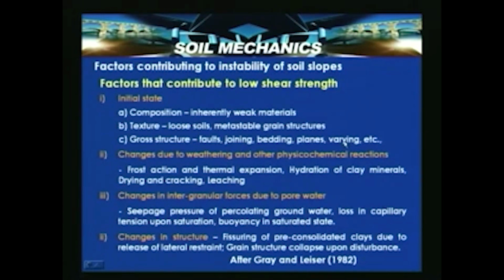Warping, planes, bedding, jointing and faults are the gross structures within the soil. Changes due to weathering and other physico-chemical reactions, frost action and thermal expansion, hydration of clay minerals, and drying and cracking and leaching, etc. can contribute to low shear strength. And changes in intergranular forces due to pore water pressure, seepage pressure of percolating groundwater, loss in capillary tension upon saturation, buoyancy in saturated state. These factors can contribute to low shear strength.